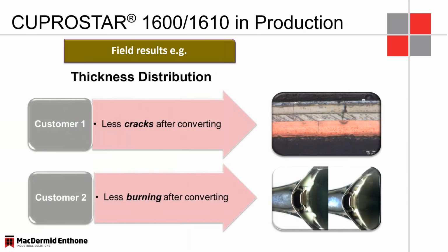We talked about thickness distribution and how important it is to be able to have thickness in the lows as well as the highs, without overplating the highs, burning the highs, and still having a sufficient amount of thickness in those low current density areas. It's hard to do with acid copper, or can be, depending on the process. We have two different situations here to highlight.